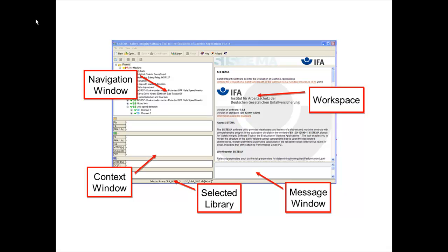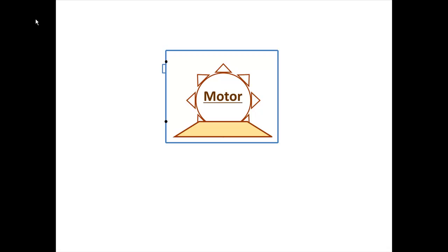A good place to start is with a simple, common safety function. In this example, we have some type of hazardous motion mostly surrounded by hard guarding with a single access point, just a simple gate. The safety function is that when someone opens the gate, the hazardous motion comes to a stop. This is commonly solved with an interlock circuit.